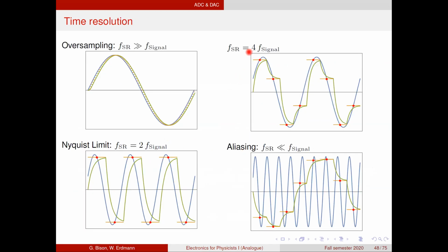But if you shift them, it's easier to compare. So you see we get an input signal digitized at this point. Over this time the output has a fixed value, and then the reconstruction filter produces something that still looks approximately like our input signal. But you see, this already changes how the signal looks.